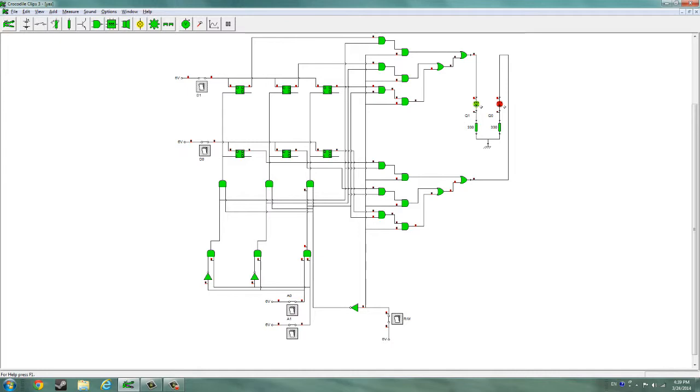For example, let's say we want to save the number 3 into the 3rd memory cell. We set both address leads to 1, hence 1, 1 is 3 in binary. Then, we set the data switches to positive, once again, because 1, 1 is 3 in binary. Finally, we set the circuit into write mode, and now 3 is saved into memory cell 3.